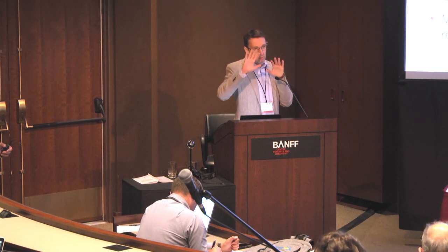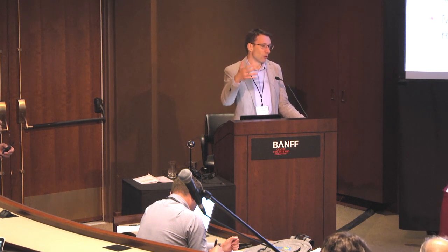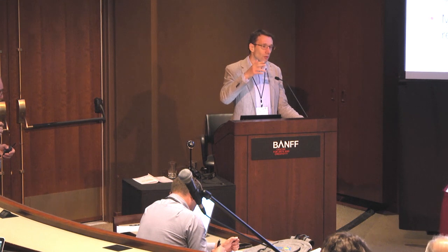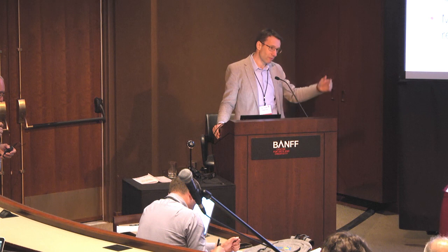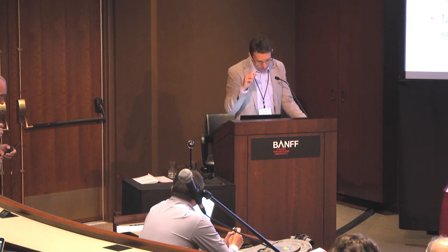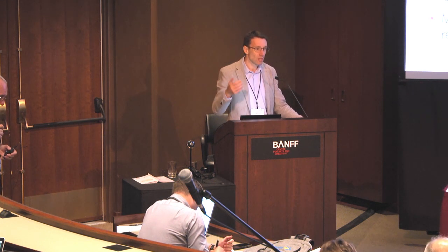Well, there are two elements. So I guess your question is, how do we forecast the load given that the load... Exactly. So, okay. We don't explicitly consider that. We just have this smart meter data, which is the aggregate load for the previous day or whatever, and we just forecast that. You can improve the forecast by including metadata. If you assume in your forecast that you also know the composition of the load, for example pool pumps, electric vehicles, HVAC systems, you can use other information, weather data, maybe usage patterns, to help you with the prediction, but we currently don't go into that level of detail.